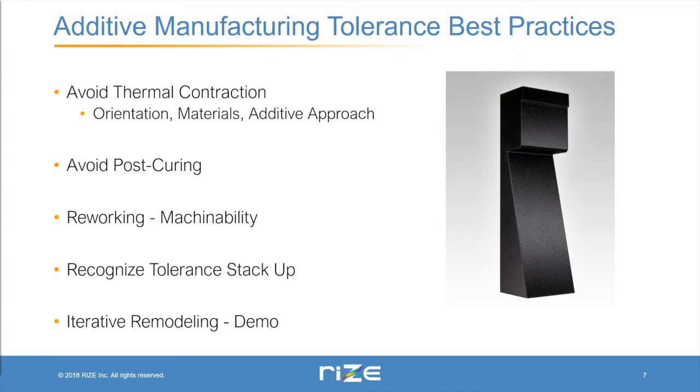Photopolymer cured resins can also in some cases be very good for machining. They tend to be a softer material, which can make them easier to machine, but can also in some cases make them weaker. And then for powder bed fusion, it will depend somewhat on the material you're using. That method can sometimes create more brittle parts, so it will not really be an appropriate material or process to use if you choose to rework parts, but some materials are all right to use for that purpose.